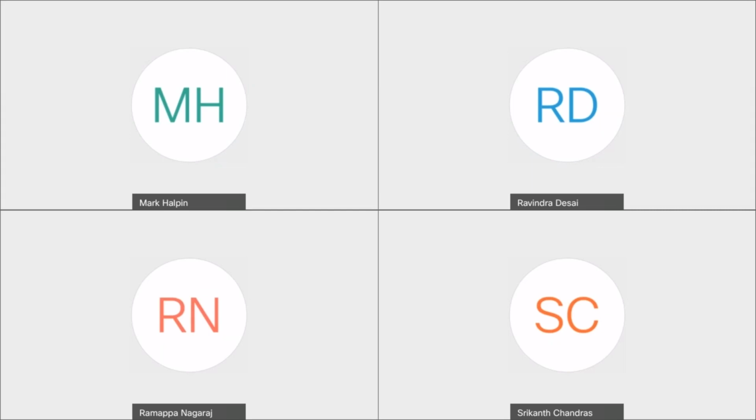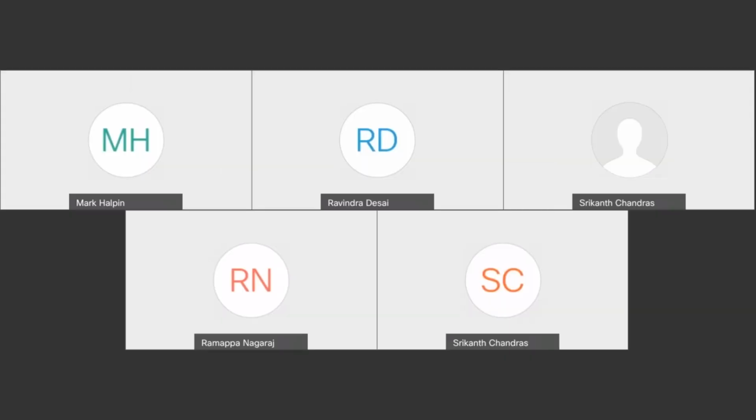Is there any limit on even harmonic emission? Yes. In the 2014 edition, all even order harmonics are limited to 25% of the adjacent odd order harmonic. So if you look at the tables for currents, you will see the odd numbers listed, but there's a note in the text that says even order harmonics are 25% of the adjacent values that are listed for the odd harmonics.